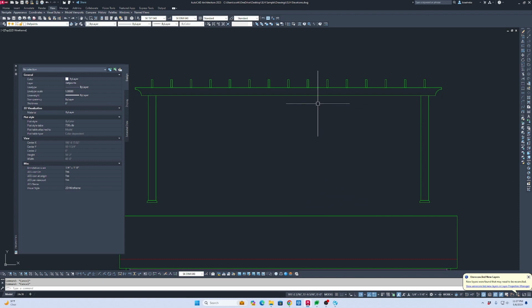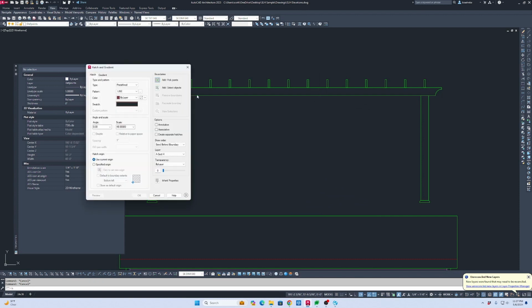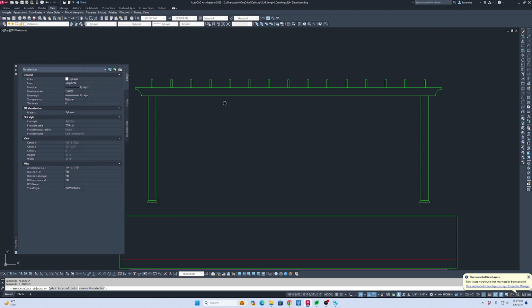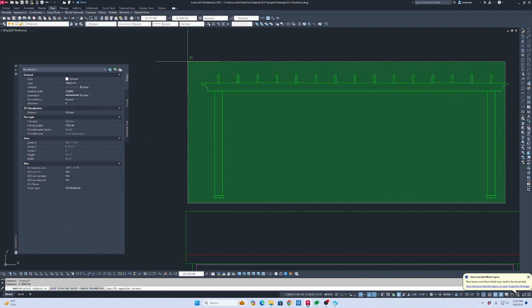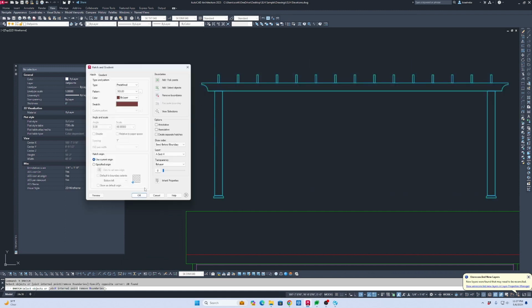Typically in AutoCAD you can do a wipeout. I do a hatch. I do a solid hatch that I have assigned to a pen of 0, so it has no thickness to it, no color. So we'll go to solid. We'll pick objects since I made these all closed objects. And I should just be able to say OK.